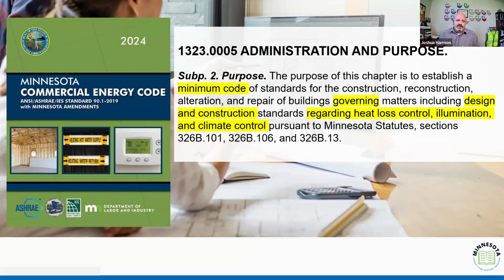Now, I had this conversation more than once this week in reference to different designs. The question is, we build buildings so tight that then we have to poke holes in them and ventilate them. Well, the reality is that while that may sound correct, and it is correct in a lot of ways, we're also able to control that air. It's better to control the air transfer than to allow air transfer unabated, right?